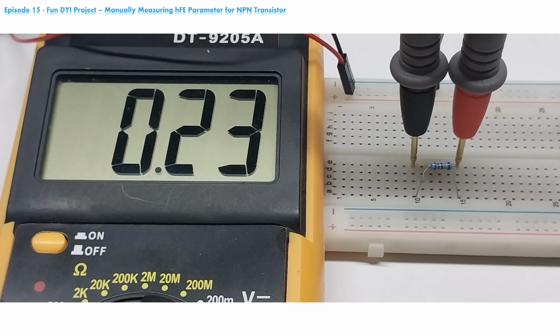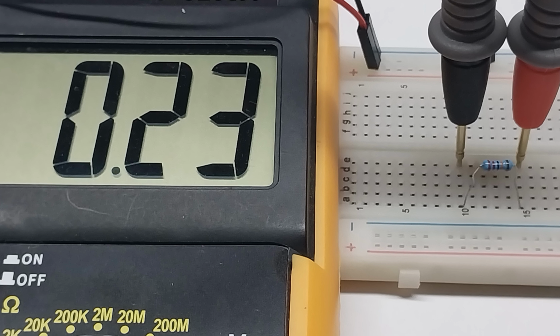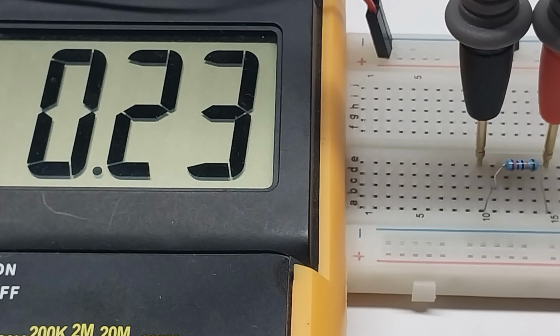When taking measurements for the value of the resistor, please take the measurement with no power source on, or current running through the circuit. If your circuit is powered on, you will not get a correct measurement for the value of the resistor. You take the measurement by placing each probe in the same slot as the resistor terminals. Resistors have no polarity, so it doesn't matter which probe goes on the left, or right side of the resistor. Set your multimeter to the appropriate range for measuring resistance, and take the measurement. Our setting is on 2 megaohms, so the measurement read 0.23 megaohms, which is 230 kiloohms, precisely.